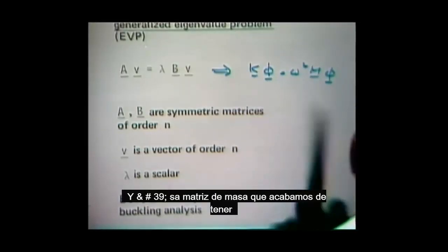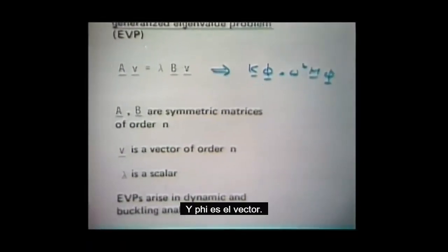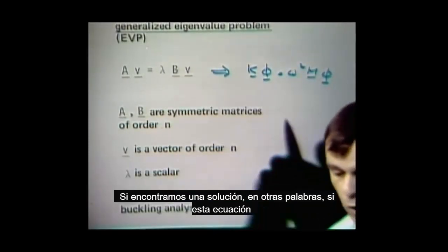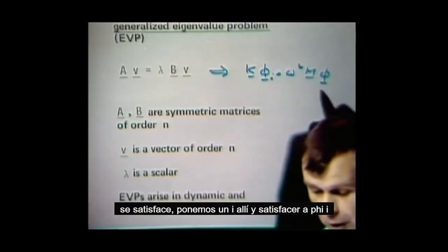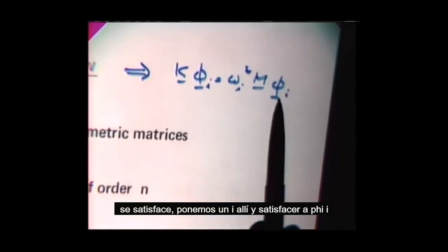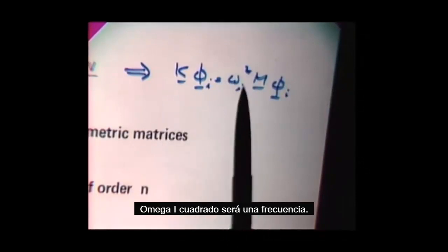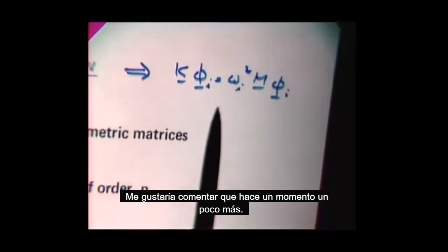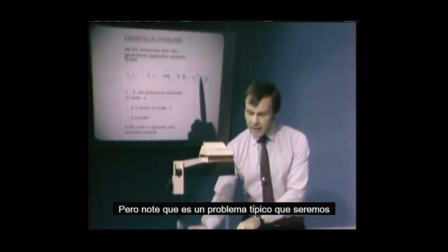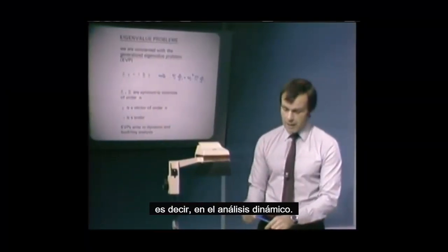M is the mass matrix that we just had here on this view graph. That is the mass matrix. And phi is the vector. If we find a solution, in other words, if this equation is satisfied, we put an I on there, satisfied for phi I and omega I squared. Omega I squared will be a frequency. I will be discussing it a little more just now. And then we're talking about an eigenpair. But notice that is a typical problem that we will be discussing, which arises in dynamic analysis.